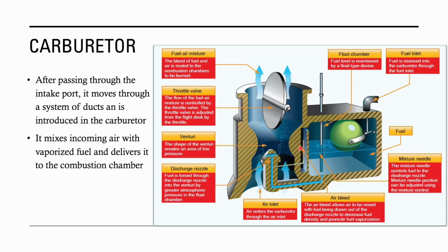So here is a simplified version of a carburetor. We use a float type carburetor. That means there's a small chamber or reservoir that stores a little amount of fuel, so that you have a continuous flow through the carburetor. If this was drawing directly from the fuel tanks, there might be some delay or it might not flow quite as smoothly.